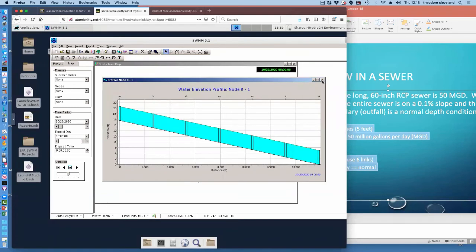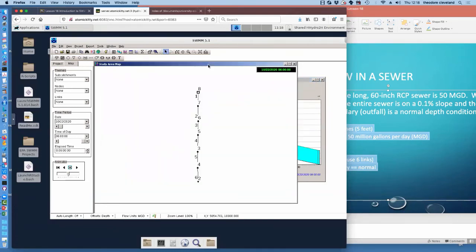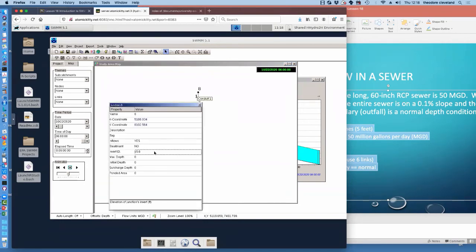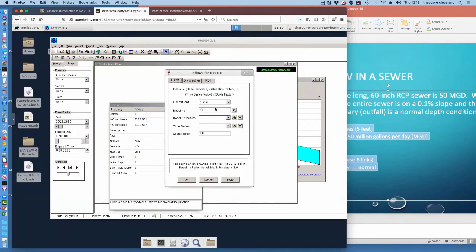So either we need to reduce the flow rate, make the pipes bigger, or make the pipes smoother. I'm going to reduce the flow rate, because making a pipe smoother, we can only do that on a piece of paper. In real life, we're kind of stuck with what the material gives us. Making the pipes bigger after we've put them in the ground is an expensive proposition.